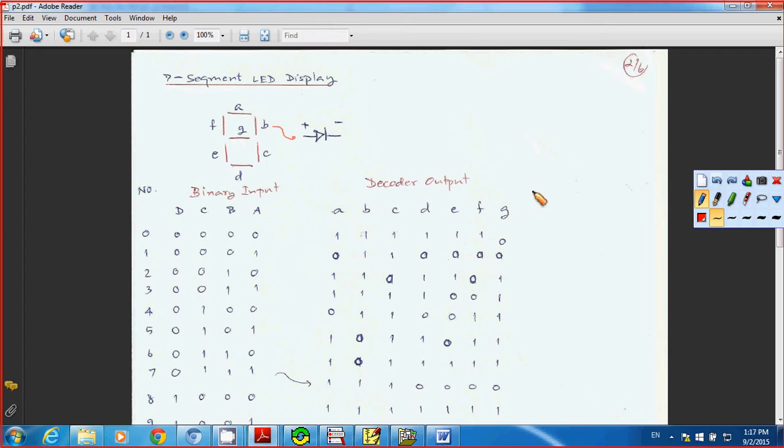Now when you take a look at the truth table, when you have 4 inputs, you can write all the combinations just like this one here. If you have 4 inputs, you have 2 to the power 4, and that gives you 16. So I break this up to be 8 with 0 for the input, and the rest is going to be 8 with logic 1.